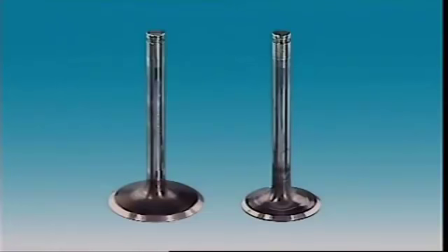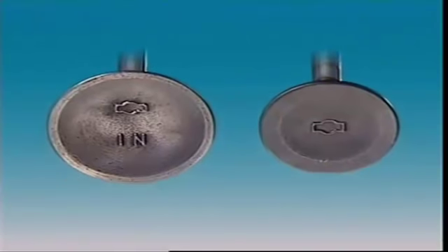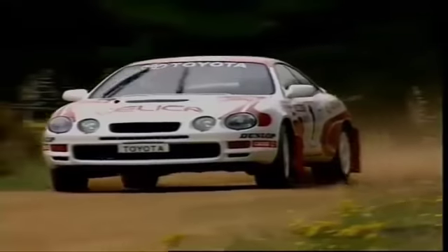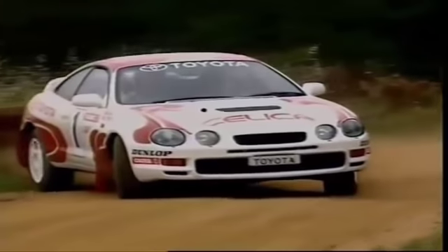Various surface treatments are used to help the valve resist wear, burning and corrosion. Inlet valves are made of steels mixed with chromium or silicon to make them more resistant to corrosion, and manganese and nickel to improve their strength. Exhaust valves are made of nickel-based alloys. Some high-performance applications use especially hard-wearing titanium alloys.